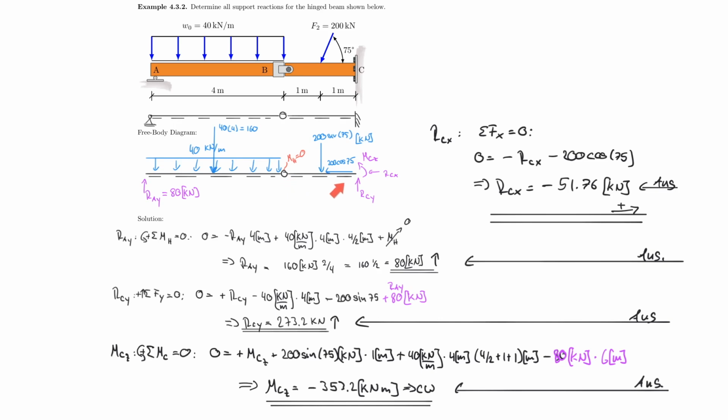But before we included all of it, we looked at only the left part of the system because we only had one unknown. We used engineering logic here first, or pretty much balance, to solve the 80 kilonewton, but we also derived it based on the moment equation about the hinge, because we know that the hinge carries a moment of 0 because it allows rotation.